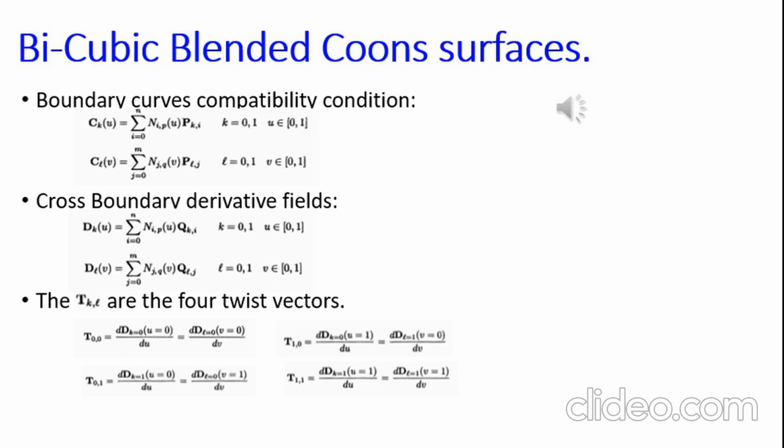We can remove this problem using the bicubically blended surfaces. These bicubically blended surfaces will smoothen the areas where the bilinearly blended cones patches have a common boundary curve, and eventually they will remove the creases that were formed. And because of this error, the bicubically blended cones patches were introduced.